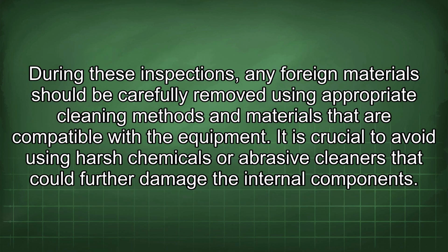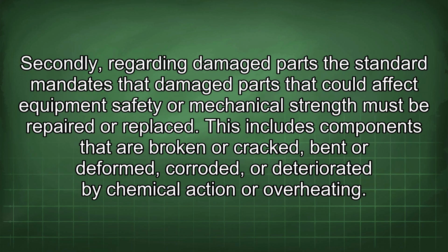During these inspections, any foreign material should be carefully removed using appropriate cleaning methods and materials that are compatible with the equipment. It is crucial to avoid using harsh chemicals or abrasive cleaners that could further damage the internal components. Secondly, regarding damaged parts, the standard mandates that damaged parts that could affect equipment safety or mechanical strength must be repaired or replaced. This includes components that are broken or cracked, bent or deformed, corroded, or deteriorated by chemical action